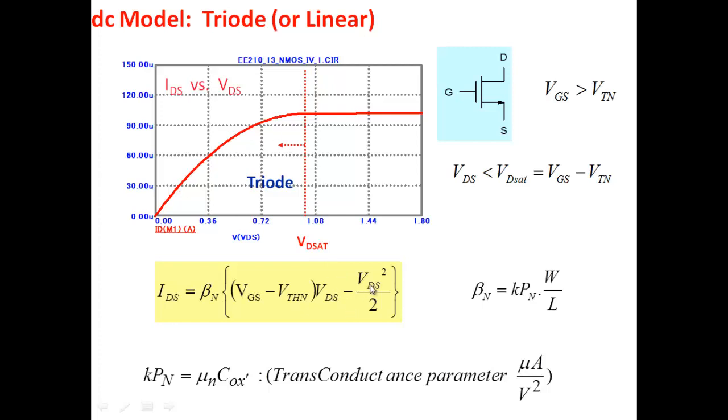So coming from this here. So many times what happens is, if we are in this particular region here, very close to VDS equal to 0, near the origin here, what we can do is we can simply approximate, we can neglect this particular part. And then you see IDS is beta n, VGS minus VTH and VDS. And so IDS is linearly related to VDS. So the MOSFET acts like a resistor. Linear relationship, anytime you have linear relationship between current and voltage, Ohm's law, you have a resistor here. So IDS linearly related to VDS, you have a resistor.